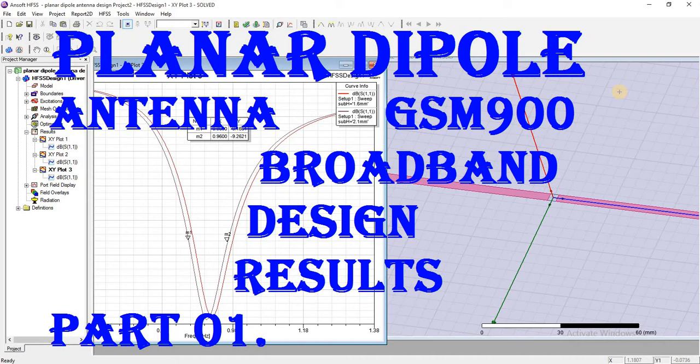Dipole antenna design. One specific type of dipole antenna is the planar dipole antenna design for GSM 900 application, for an operating frequency of 0.85 GHz to 0.95 GHz. It will give us a broadband, a large bandwidth, as compared to a simple vertical dipole antenna.